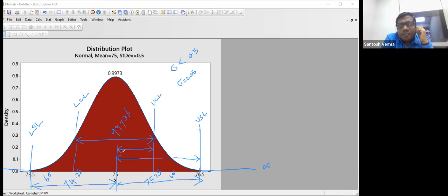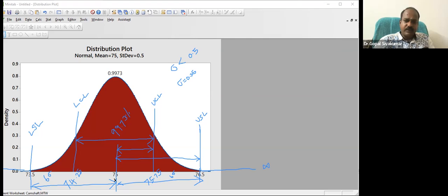Yes. Similarly, customer has given you a tolerance. 75 to 76.5, 1.5 mm tolerance, both sides. But how much tolerance does your process consume? Half of it. The balance will save you when there is a necessity. When something goes wrong, the balance will come and save you. Logical? Since you are consuming only half of the tolerance, you have made your process doubly capable.